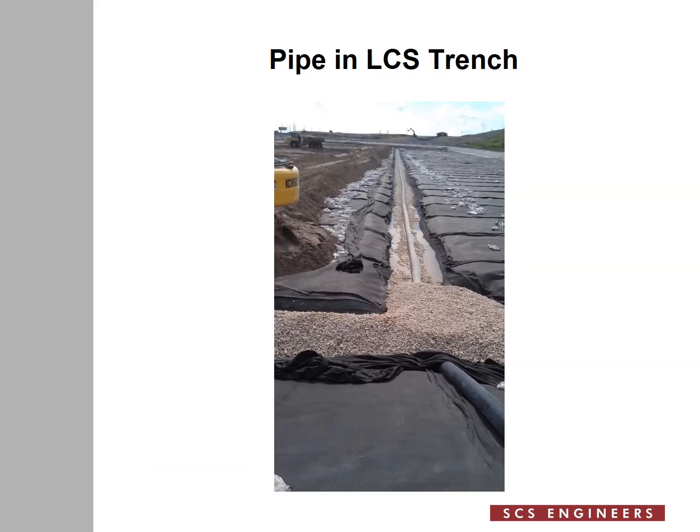It shows the pipe sitting on top of the 3-inch thick layer of gravel, and to the left side you see the textile that will be pulled over the final stage of gravel after the gravel placement is complete.